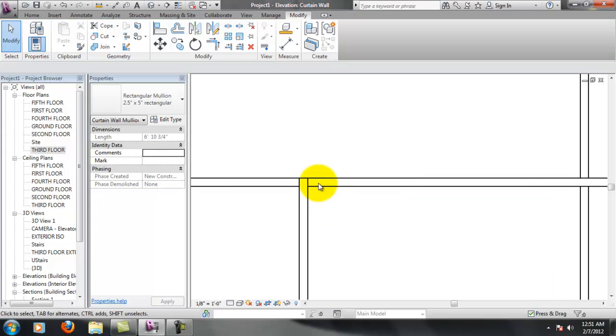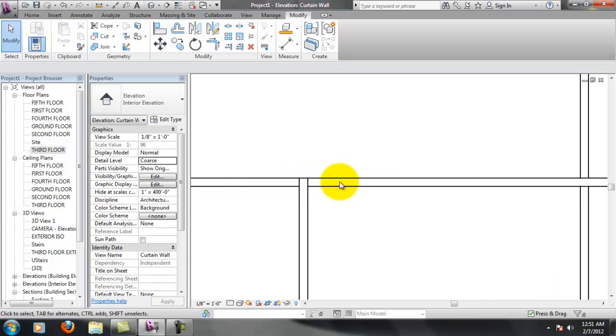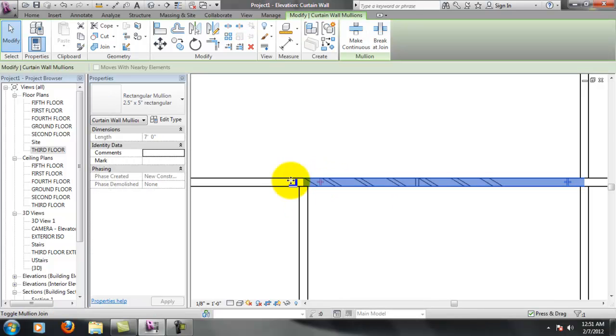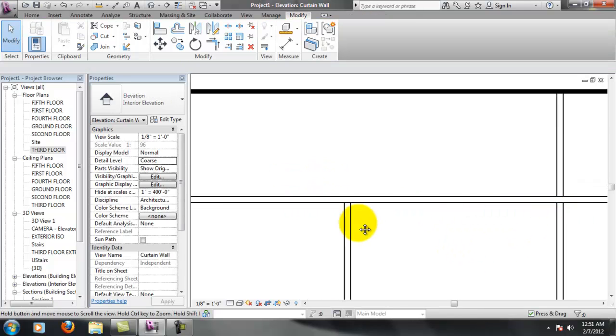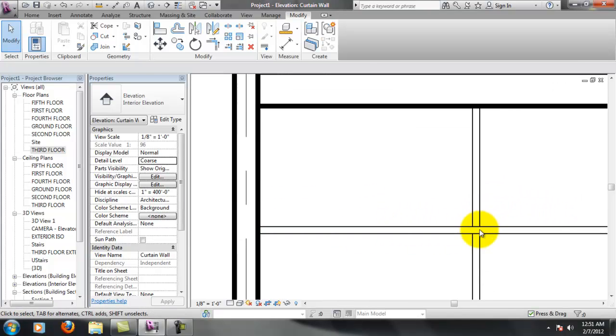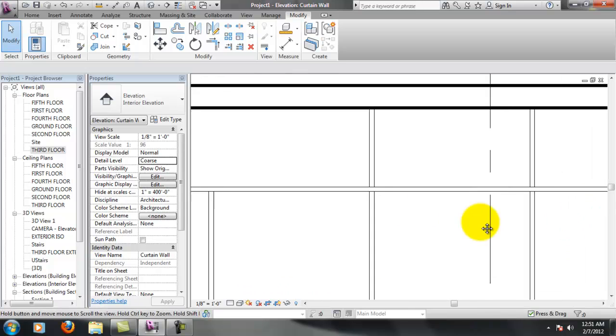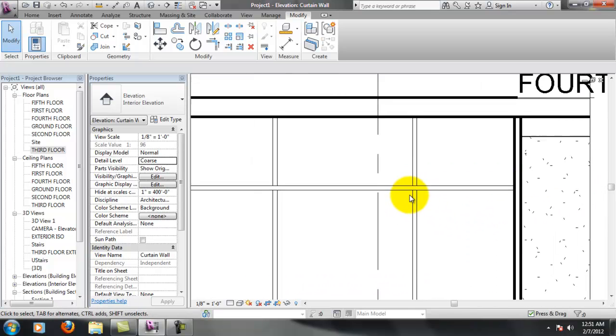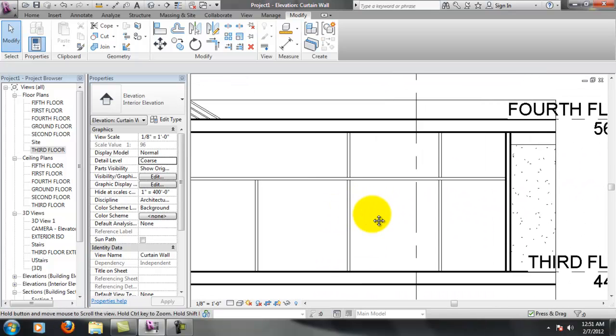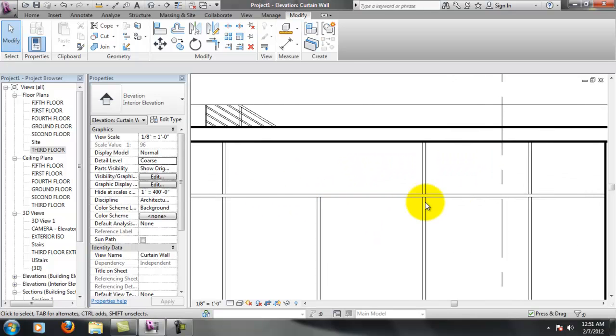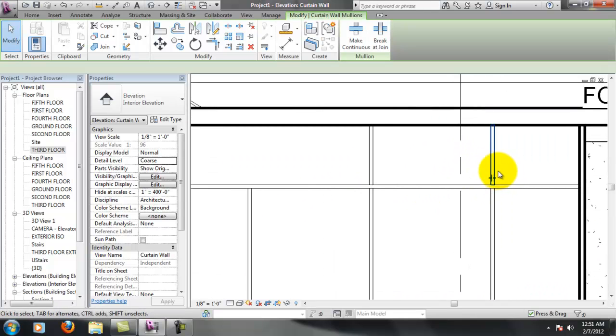If you select these symbols, it basically either makes the horizontal mullion run all the way across, or it makes the vertical butt end. I would imagine you're going to want this to be solid all the way across, like this, and your frame for the most part will probably sit on top. I guess it would probably be different from design to design, but for this I went ahead and added that little feature.